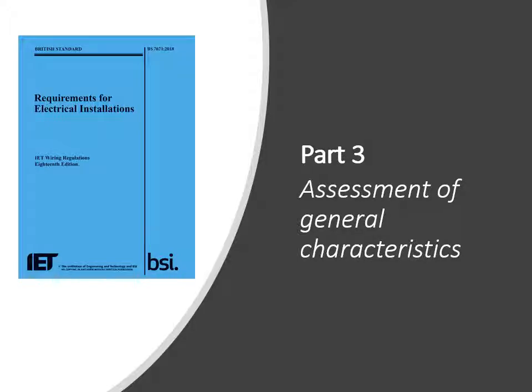So as you see, part 3 is an assessment. It's having a good look at what we're expected to produce. What are we going to design our system to do? How big the demand is, what kind of supply voltages and things we need, what kind of protection, not just for overcurrent, but what other protection services do we need? Protection against fire, protection against external influences. All of these factors need to be built into our initial assessment and planning before we can get into the actual design and creation of our system.